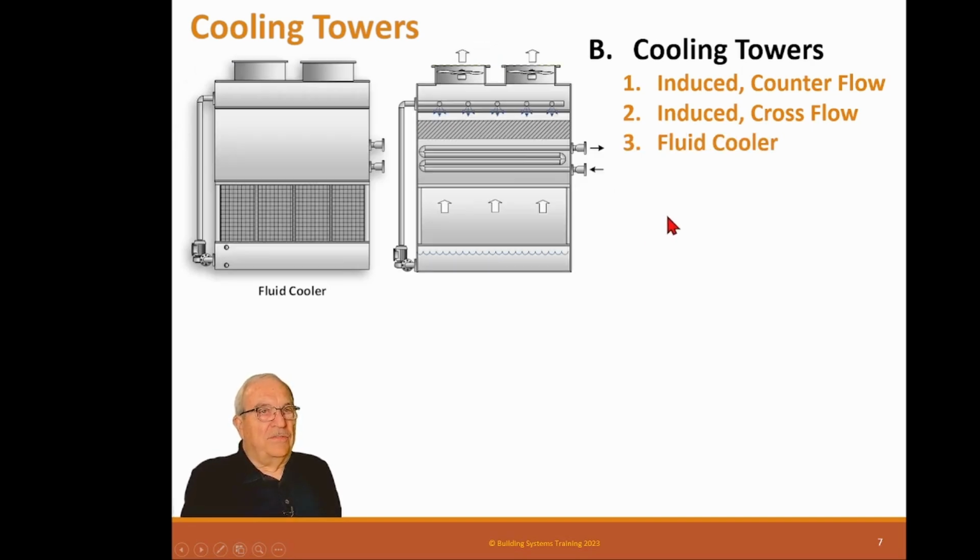This is what we call a fluid cooler, and a fluid cooler is basically a regular tower that has a water basin on the bottom with a pump, and the pump pumps this water up and over the fill. This is the tower fill, and as the water comes through, the air coming up cools the water and gives an evaporation effect so the water gets cold. It then flows across this heat exchanger bundle and wets the bundle, thus removing the heat from the condenser water.